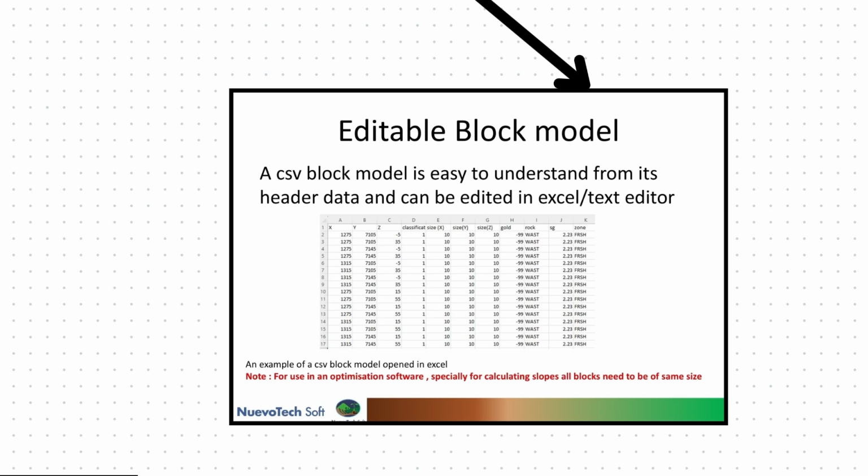As a tip, always double check your block dimensions column is constant, obviously. If not, when you import this into MineOpt for scheduling, the model may be rejected. The note on this slide remains: for optimization, like calculating the pit slope, all blocks must be the same size.